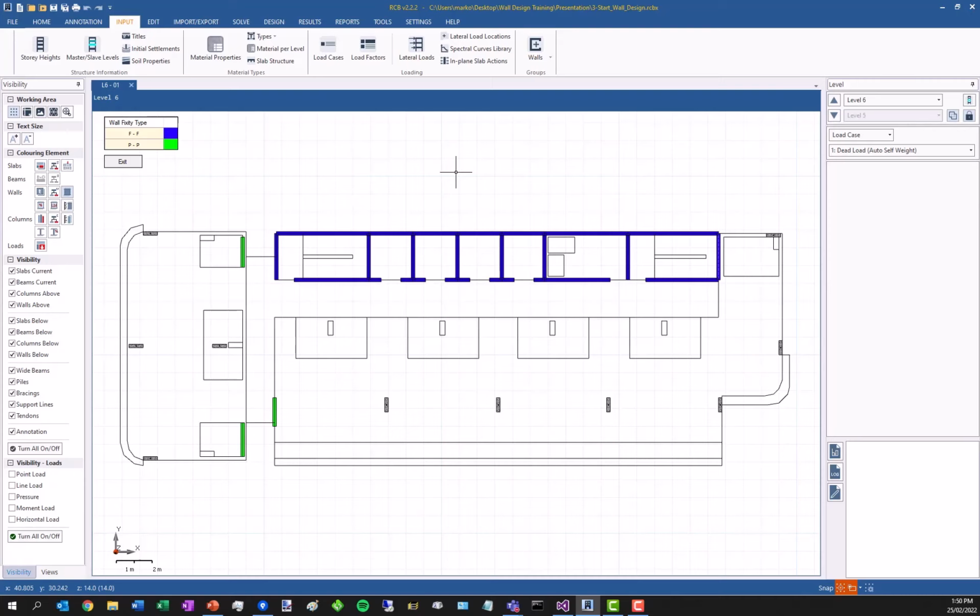Essentially, a different set of design settings will be applied to the wall if we use the default design settings based on the fixity that we modeled. This is based on the old school idea that our shear core will form our lateral resisting system. So the shear core is fixed, and everything else will be a vertical only element, and will be modeled as pin.